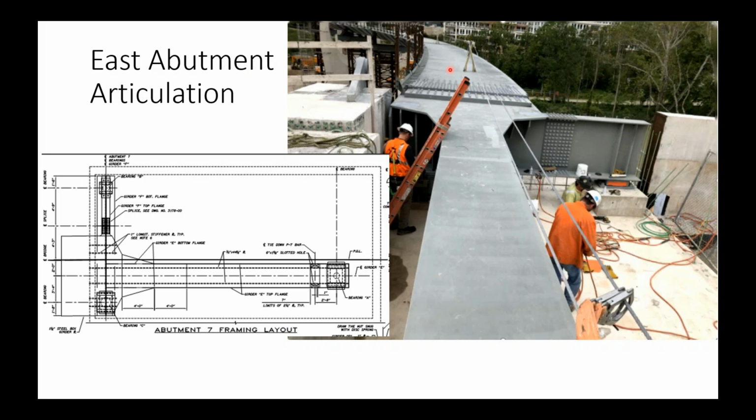The other thing that we notice here is on the extension of this bridge. Normally this would be a pin support, and most abutments are just a pin support, but in this case, most suspension bridges are continuous, and the span to depth ratios that we talked about, the L/100 for a continuous, is really targeted at a continuous bridge.